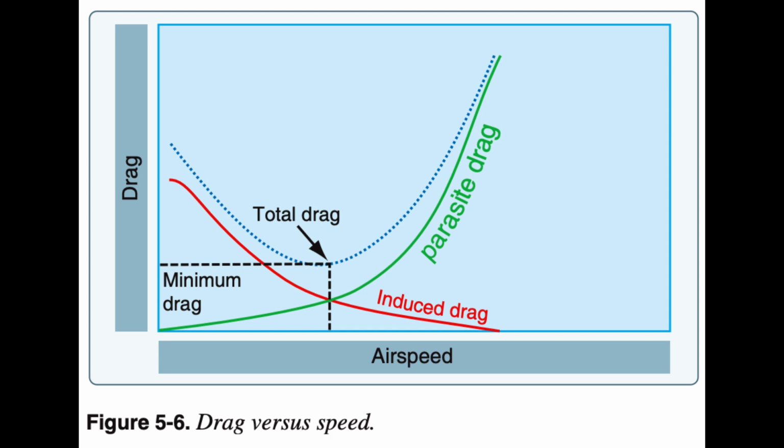Parasite drag. Parasite drag is comprised of all the forces that work to slow an aircraft's movement. As the term parasite implies, it is the drag that is not associated with the production of lift. This includes the displacement of the air by the aircraft, turbulence generated in the airstream, or a hindrance of air moving over the surface of the aircraft in airfoil. There are three types of parasite drag: form drag, interference drag, and skin friction.